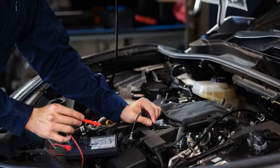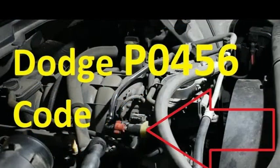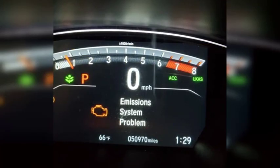The most common symptom of code P0443 is a check engine light. However, you may also experience other symptoms, such as difficulty starting the engine, rough idle, stalling, increased fuel consumption. There are several possible causes of code P0443, including a faulty purge control valve, a leak in the EVAP system, a problem with the wiring or connectors, a faulty fuel cap.